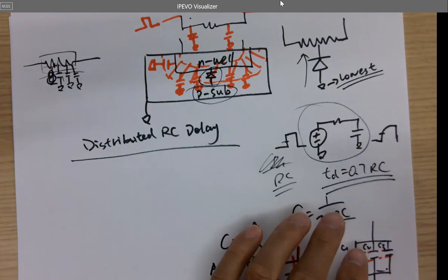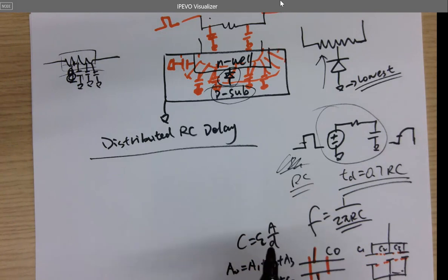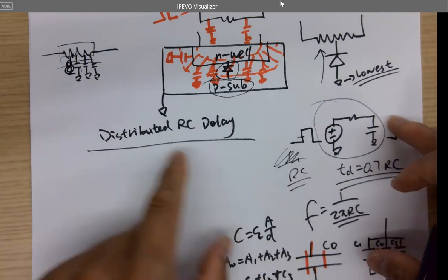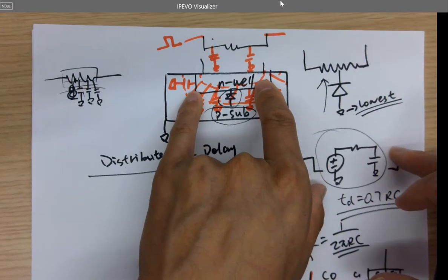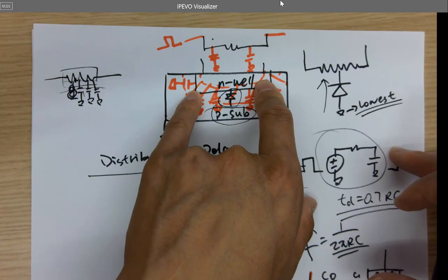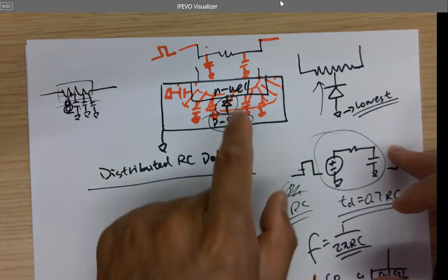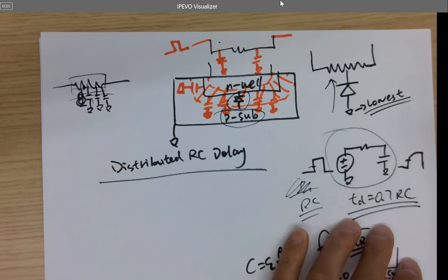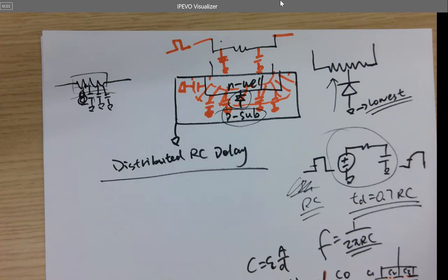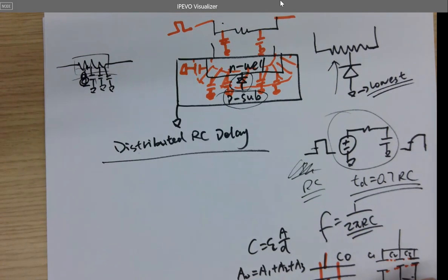This is a resistor that has some undesired embedded capacitance we have to consider, because it's causing delay. If we design the resistor, we are not intentionally making a capacitor or getting some time delay, but it's going to cause time delay because of the parasitic capacitance. So we're trying to understand how much delay it's going to cause in order to take that into consideration for our digital design. So we cannot make our circuit too fast because of the delay, right?